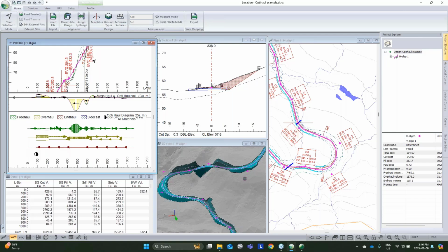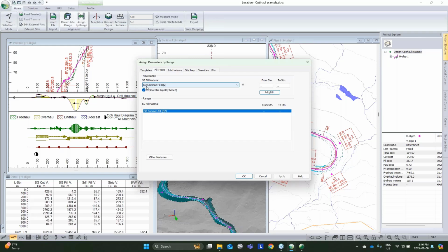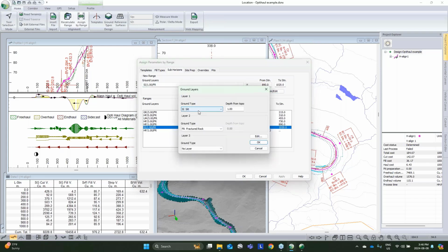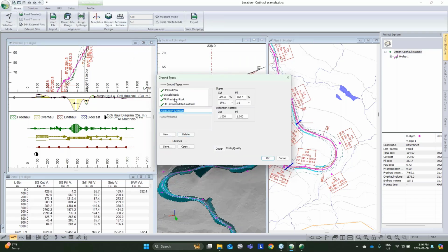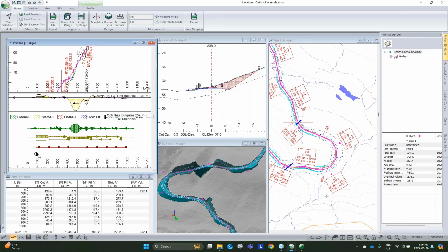Well, why is that? The way we have this set up, we've got some silt out at the end. I want my subgrade material to at least be made out of material that is Q2 or better. That silt material that I'm looking at is Q1, so when I set it up, I'm saying it's not usable, and that's getting hauled back to be disposed of.